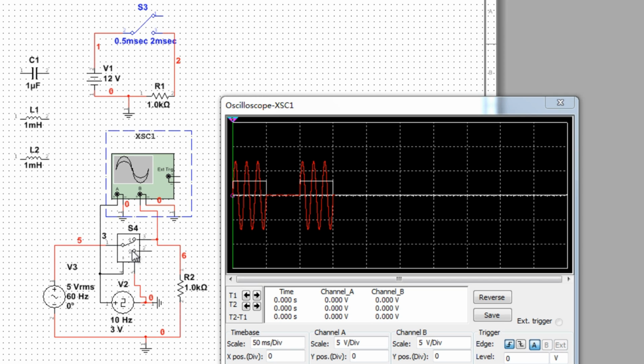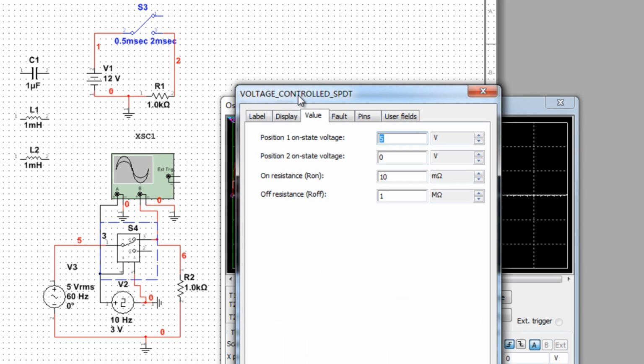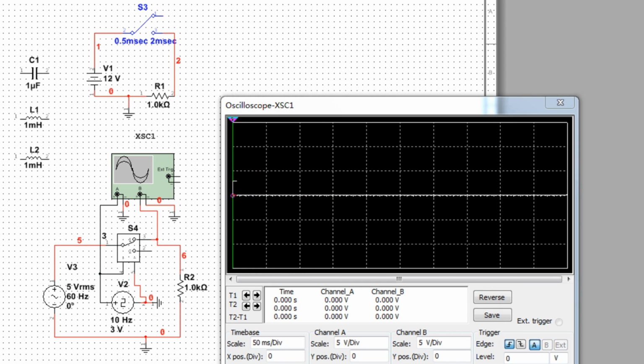connected to 2. We need to make note that in this voltage-controlled SPDT switch, there is a threshold for the opening voltage. In Multisim, this value is not accurate. Please check that if the voltage is accurate, the input signal needs to reach 5 volts to open the switch, but now 3 volts can open it. To verify it, we can set the parameter as 50 and do the simulation again. See? Now 3 volts will never connect terminals 1 and 3.